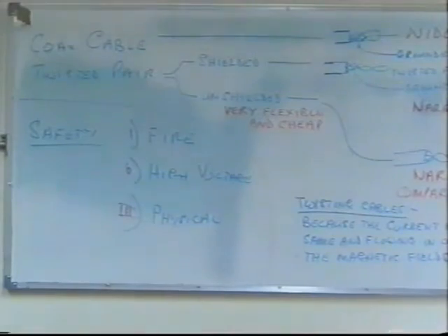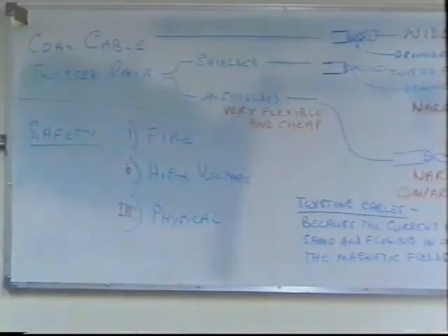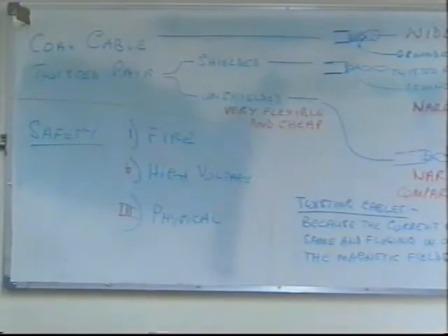Why would they use safety locks? There should always be safety locks of some sort for most high voltage applications. For instance, in a large power transmitter where there's a chance of high voltage, if you open the door, it's supposed to operate a micro switch which will cut off the power so that it's safe. But of course, to service it, you need the power on, so there must be some way of overriding that. And that's when the danger comes, when you override the power.